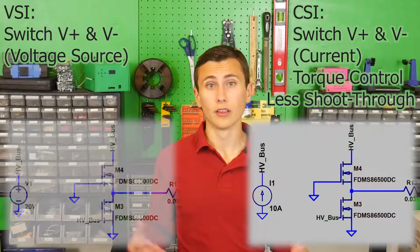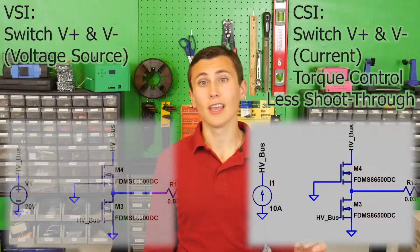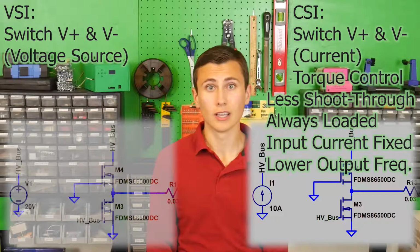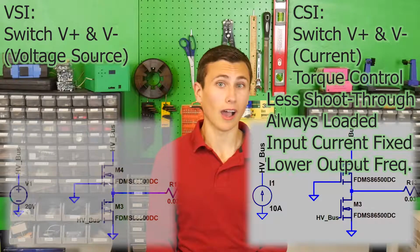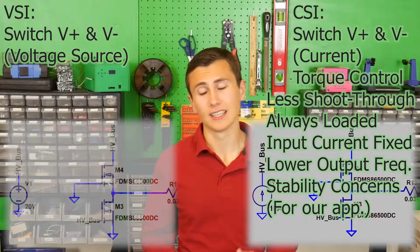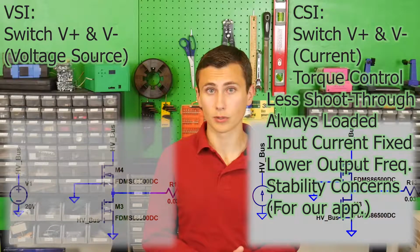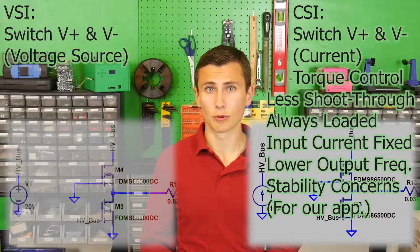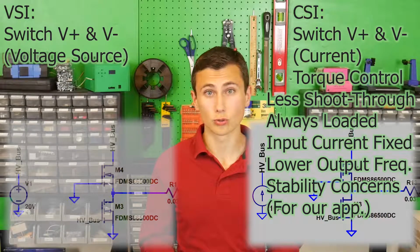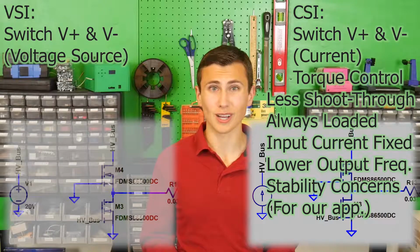With that said, the current source inverter operating principle relies on a minimum load current and has a lower maximum output frequency than a voltage source inverter. Specifically, the light load, high frequency mode of operation is especially unstable. I mean, it has some pros. The current source inverter has some pros, but I just don't think it's going to work for our topology. We need our power supply to operate under light load and have good transient voltage regulation performance, so the current source inverter is pretty much out.